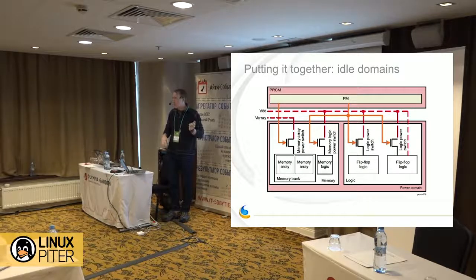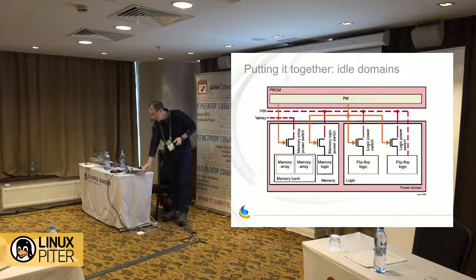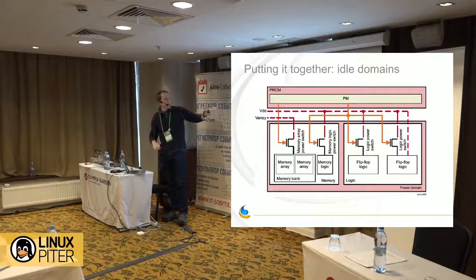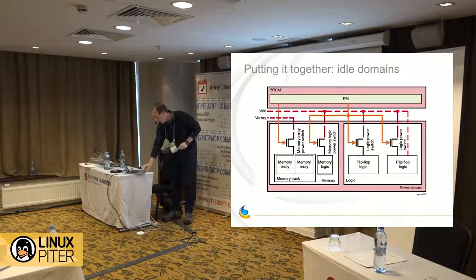So, in the previous slide we talked about clock gating. Now we're really talking about changing the power that we supply to these modules. This is an idle power management thing. If we lower the voltage or cut power to an idle domain, it's because no work is being done on these modules. They're idle. They're not doing stuff right now.